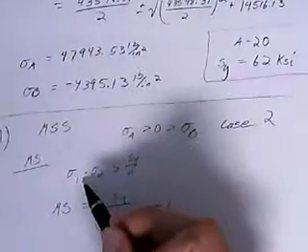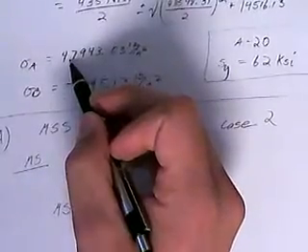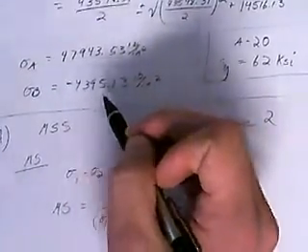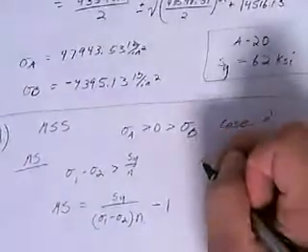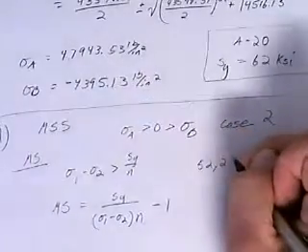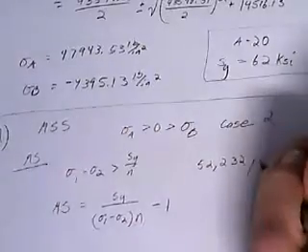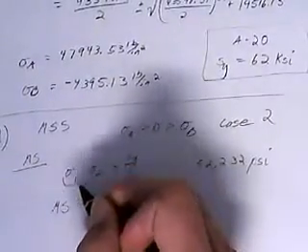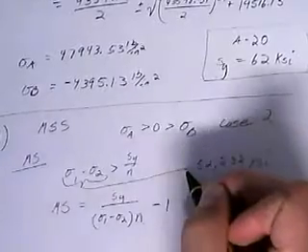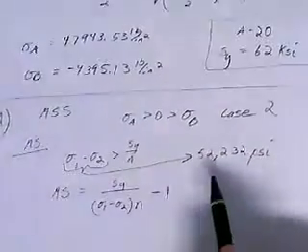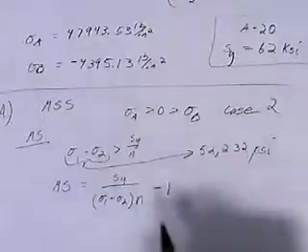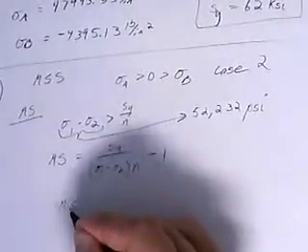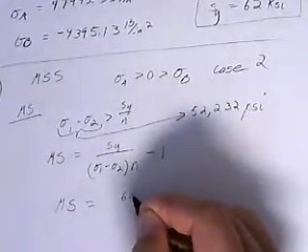Now, if we do this calculation of sigma 1 minus sigma 2, this one over here, so 47 minus the negative this, you'll end up with 52,232 psi. So this is what this value is, so make that clear. So subbing this in down here and using the Sy that we found up here, you can find out the margin of safety is equal to 62.